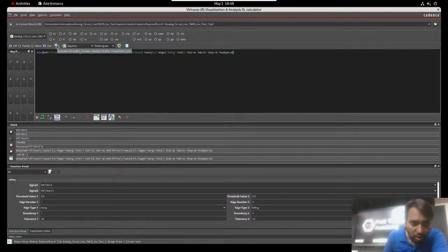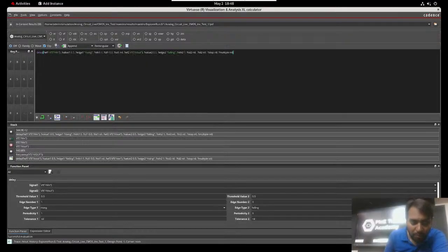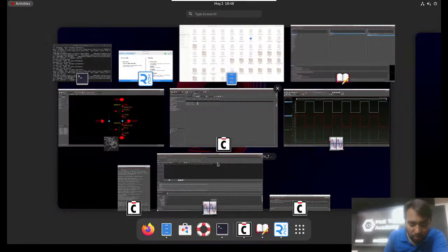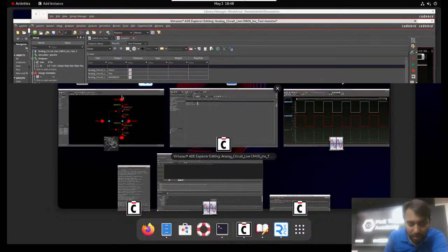If you click on that, you will find that delay. Okay, so you have a delay of 344.9 picosecond, or you can press apply, and you can go for that window right here. So that will be ADE. You can go for Maestro here. In the Maestro you will check that.